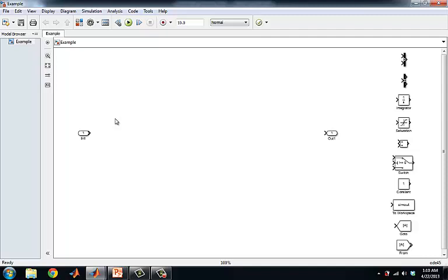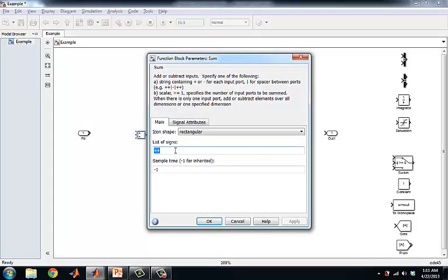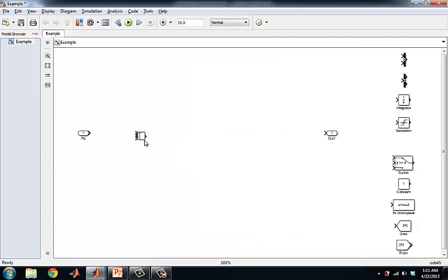So in this equation we're going to be solving for the inertial force Fi with FTR as an input, and this is one of the inputs that we're going to use, so I'm going to call this FTR. And then in order to generate this equation, I'm going to need this sum block here, and it only has two inputs, so in order to change that, you want to double click on it, and you can change the number of inputs it has. So I want 1 plus for the FTR and then 3 minuses for the rest of the resisting forces. You can resize this to make it a little prettier and connect FTR to the positive port.